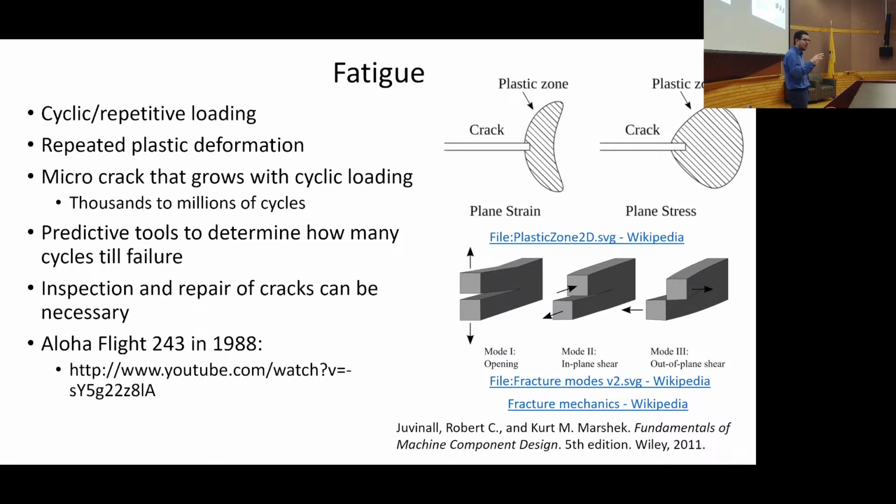So let me not scare anyone. Let's not be too subjective; let's be a little more objective here. Do you think the need for inspection is greater with planes that make lots of short hops and flights, versus planes that just go longer distances and don't do as many landings and takeoffs? Yes, short hop flights would be more. Right. Why is that? Takeoff and landing add more stresses to the structure. Yeah. What is the load on a plane that you're getting that's fatigue based here?